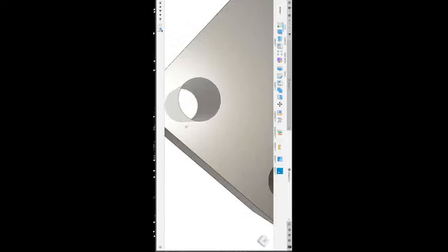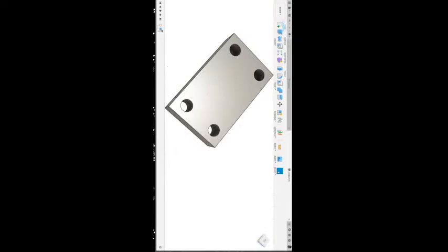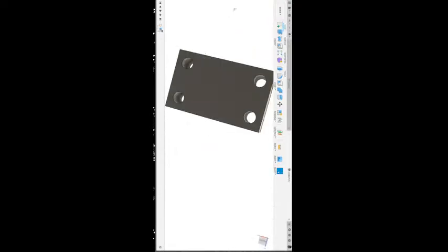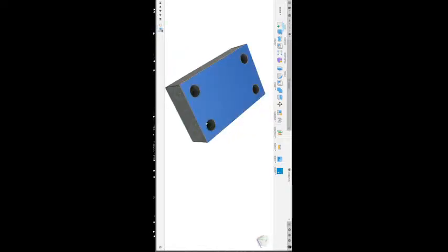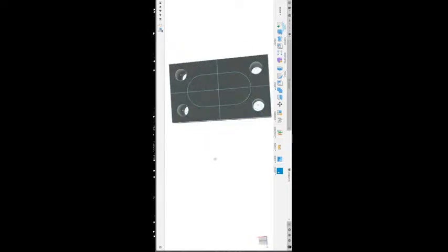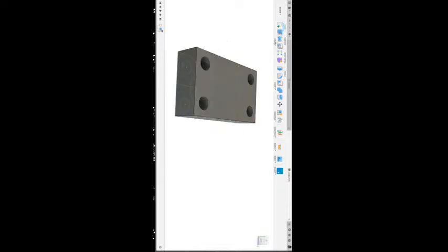So we just made holes here. We just need this profile to be here, and it should have a depth of 3 mm. So you can ask me how it is possible. And how do you bring this here? By move? No, it is by extrude.